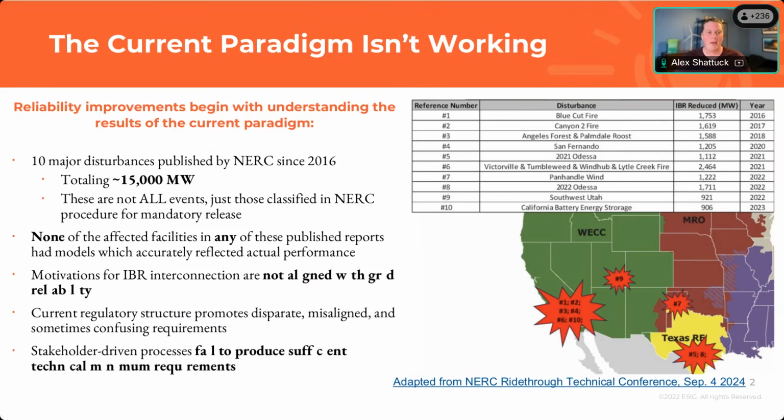So what happens very often in wind facilities is you may see something called a partial trip, which is maybe half of the wind turbines trip offline, but the rest stay online. That means you may have an event where 10 PV plants trip offline, and they're 100 megawatts each. That's 1,000 megawatts tripped offline. You may have a very similar event where 10 wind farms of 100 megawatts each partially trip, and that's about half the size. Just for example.